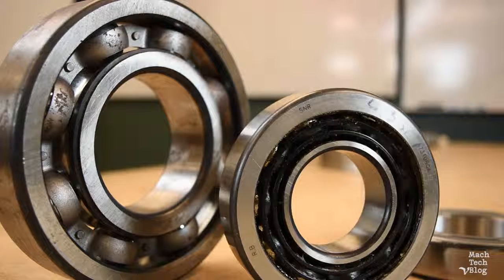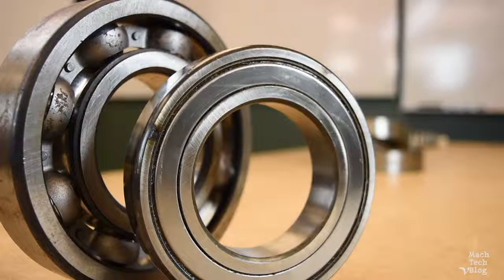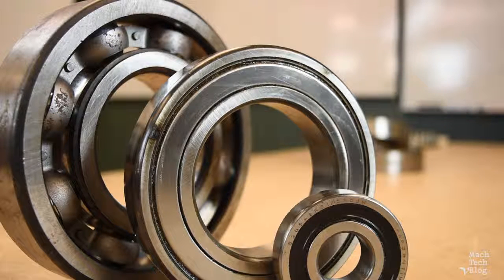Here's the same type of bearing, but notice that whereas the first bearing has a cage made out of stamped steel, this one has a cage made with polyamide, a type of synthetic polymer. Here's the same bearing again, but notice the metal shield protecting the bearing elements. This is one of those optional accessories I mentioned. The other type of common bearing protection is the elastomer seal. Both shielded and sealed bearings are pre-filled with grease at the factory and are considered lubricated for the life of the bearing.